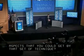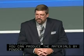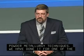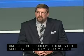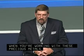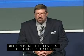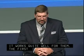Yeah, I'll start with the second question. You can produce these materials by powder metallurgical techniques. We've done it for one of the high temperature shape memory alloys, the nickel, titanium, palladium materials. One of the problems there is really the yield for your powder processing. Your yield is probably about 50% of your original melt. So when you're working with these precious metal containing alloys, to have such low yields when making the powder is a major disadvantage, but you can produce these materials through conventional powder metallurgical techniques, and it works quite well for them. The first question, I don't quite understand what you're asking about in terms of the hysteresis of the strain.